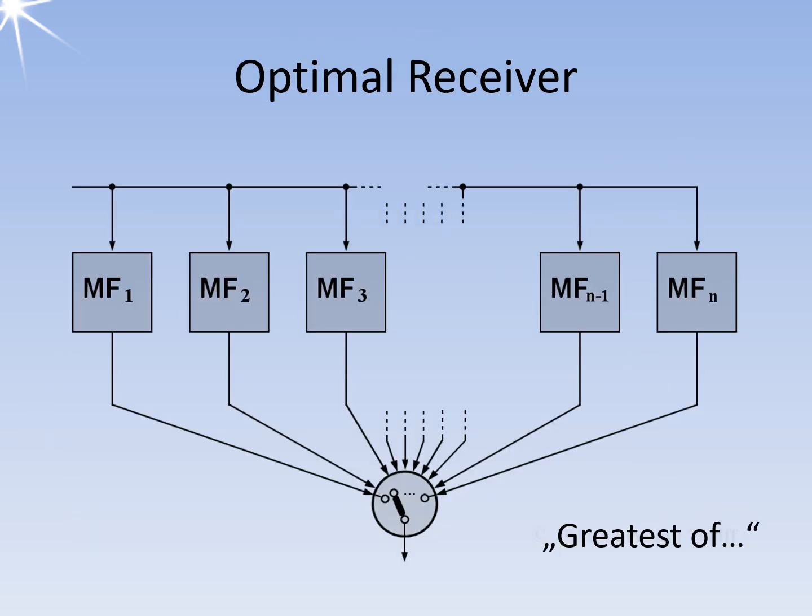The image was taken from the video matched filter, which is why the abbreviation MF for matched filter is still shown here. A matched filter or a matched receiver would only be possible if the shape of the input signals were known. Unfortunately, with radar, the shape of the signal is not known. Of course, the echo signal should look approximately the same as the transmitted signal. But only approximately. The echo signal is changed in shape by the Doppler frequencies. All these changes contain important information about the target.